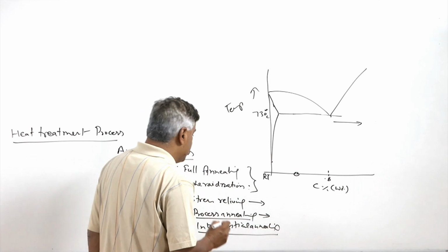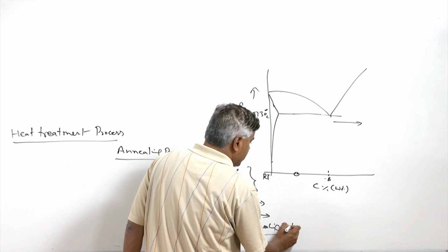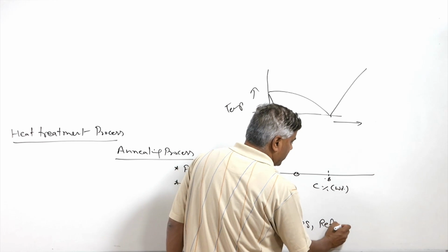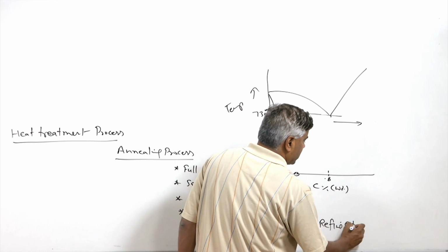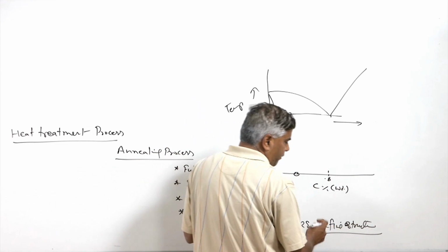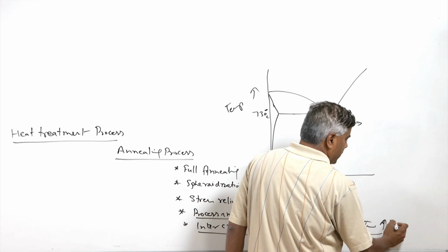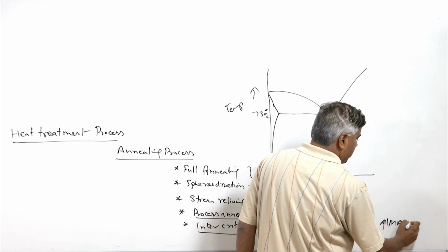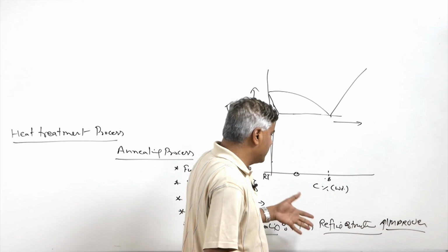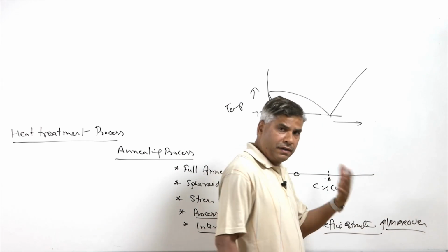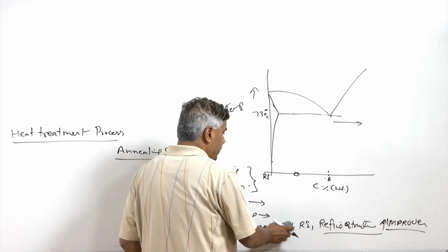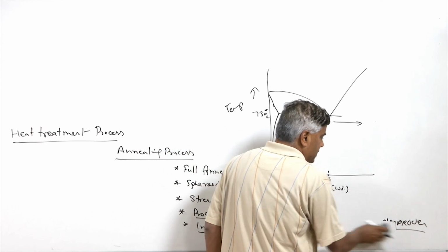Then coming to intercritical annealing. This intercritical annealing will not just be reducing the residual stresses, but it also refines the grain structure significantly. So in which way does the refinement of the grain structure in turn improve the mechanical properties? Basically, reduction in residual stresses, refinement of the grain structure, recrystallization of the grains, and improvement in mechanical properties are obtained when the intercritical annealing is carried out.